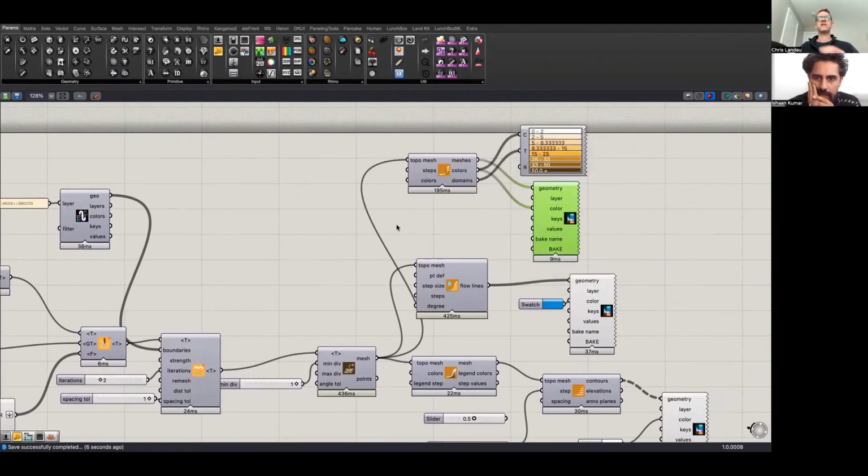And then if I want to change the slope analysis, the gradient: the way the slope works, there's a set of default values. It goes from 0 to 2, 2 to 5, 5 to 8.3, 8.3 to 15, etc., and then 50 to a very, very high number. It's not infinity, but it's really big. So you have 1, 2, 3, 4, 5, 6, 7, 8 steps. That means you need 8 colors.